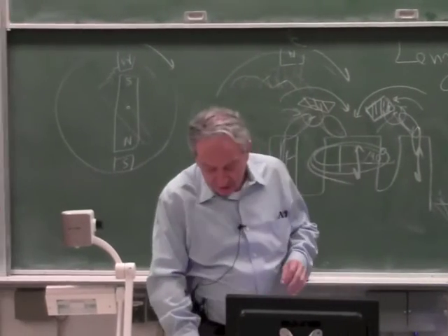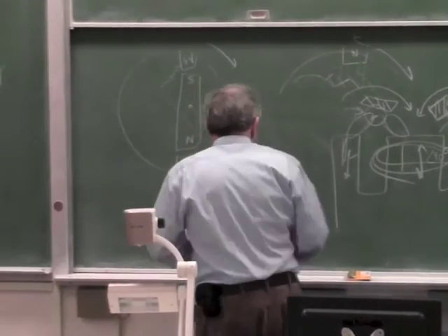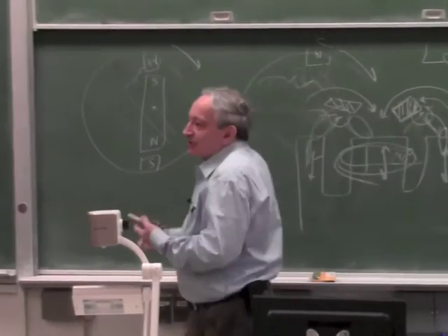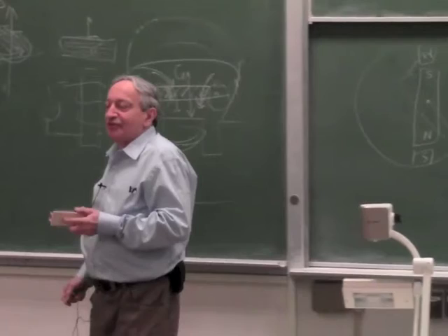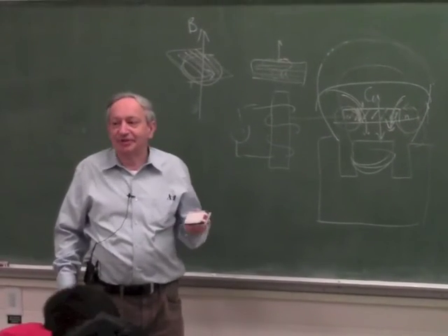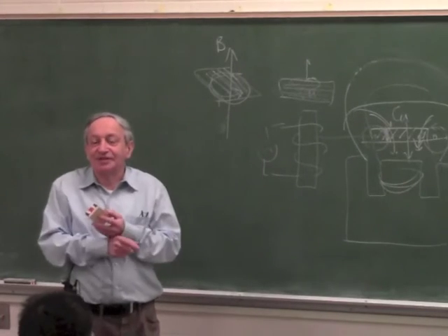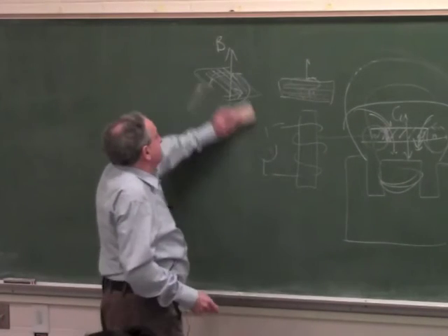So the two things I want to finish up the motor section with are how you reverse direction for the different types of motors. The easiest question is, how do you reverse direction in a rotating field motor? Everybody should remember that. What do you do? Switch two phases. Because if you switch two phases, it's the same as reversing the field.